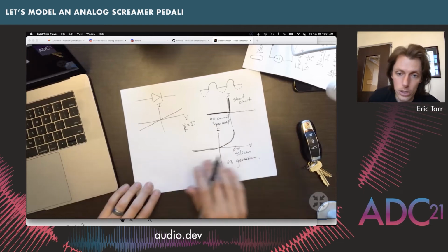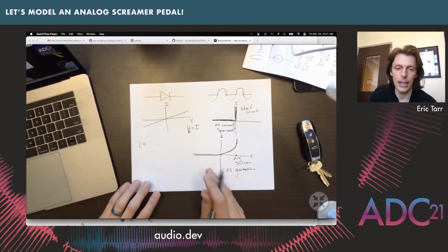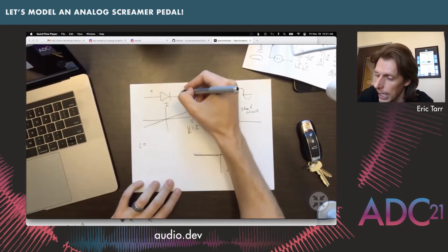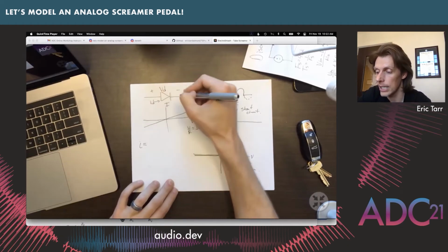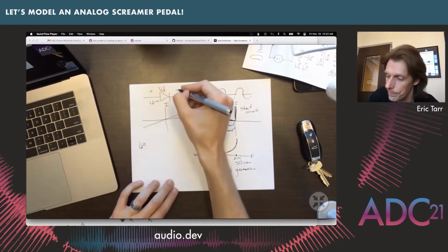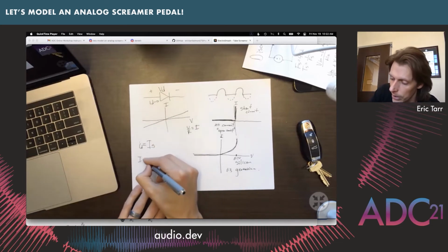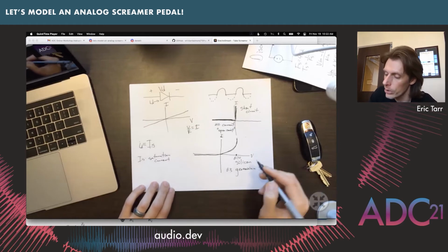There's an equation that we can use called the Shockley diode equation, where we have the current here is equal to some constant variables that we're going to set as part of it. And then there's a voltage that goes across the diode. So there's the current ID that goes through the diode, and there's a voltage that goes across the diode like this. So our equation between the current going through it and the voltage across it is the saturation current. That's a thing here called saturation current. This will depend on the type of material we use.